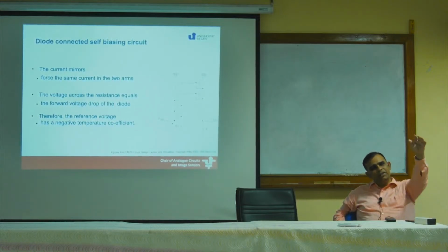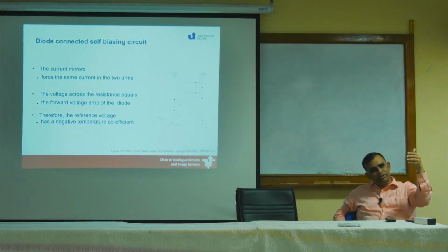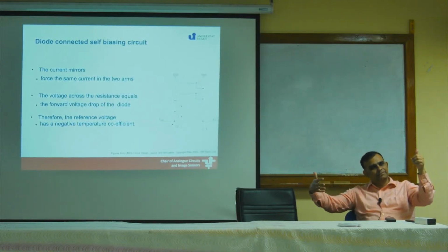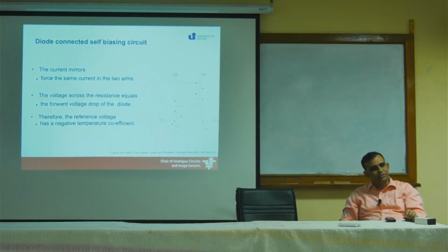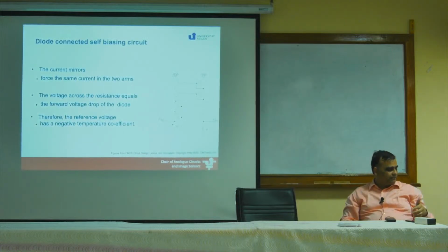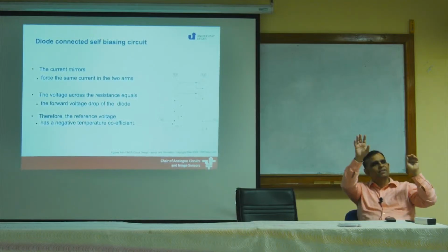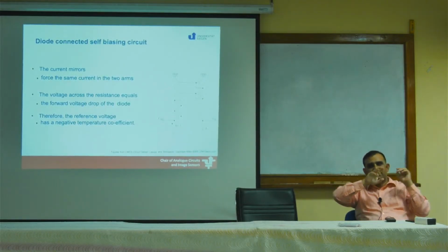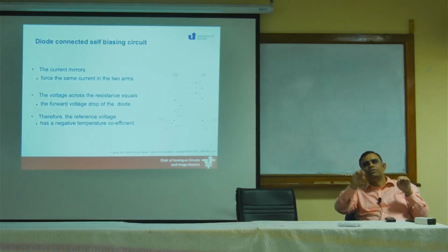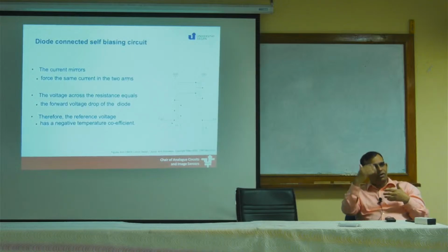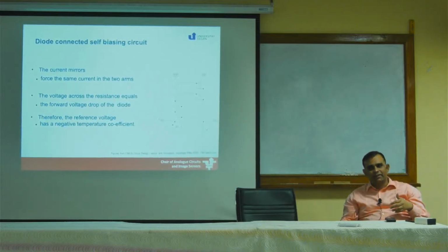So, if we have one source which is n times or 2 times the previous one, and another source just as it is, and I subtract these two, because my current is in log domain, say my voltage was a plus log of temperature, and the other one will become 2a plus 2 log of temperature. If I subtract these two, log T will cancel out.